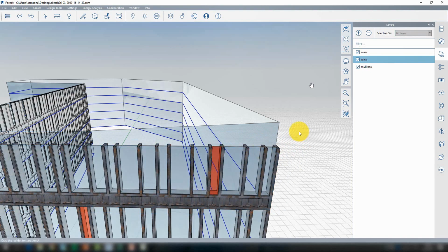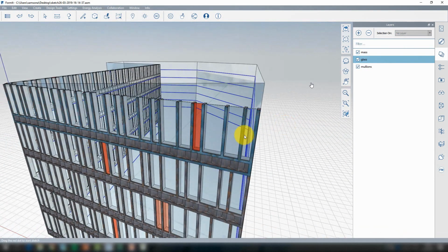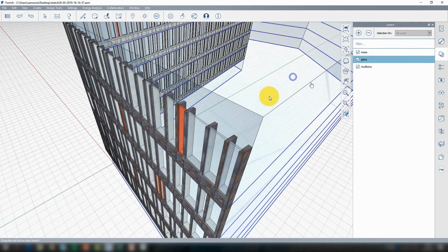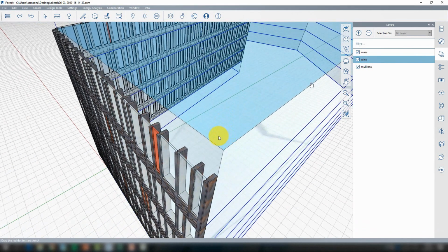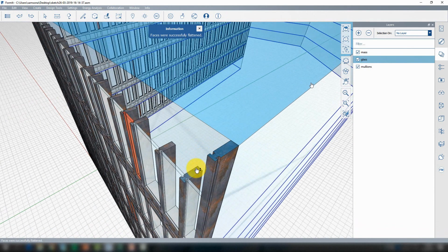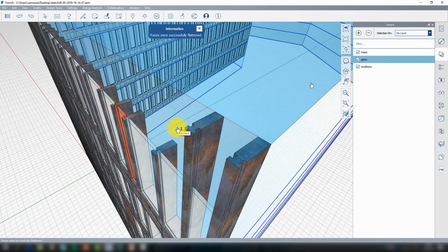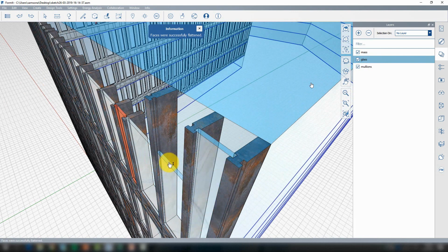It becomes a little bit more complicated, right? But what can be done here now is that I can ungroup, so I can basically explode this instance created with the script, and now I can start to modify completely manually every single element that has been created with Dynamo.